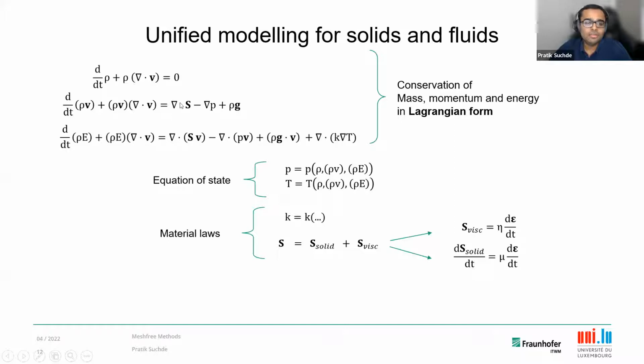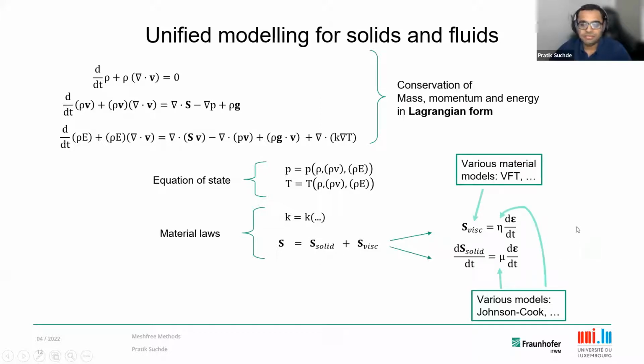And we are essentially using the same kind of system for also modeling solid flow, so to say, deforming solids. So the stress tensor that you see in the momentum and the energy equations will also have a solid term, which can be governed by different models. For example, a Johnson-Cook model, or a Drucker-Prager model for sand or something like that.